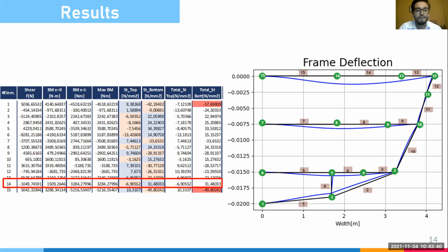There is a positive bending moment, and the fibers at the top are in contraction, so it makes sense; according to the graph they are consistent. And another thing, in that part of the beam we have to take care because it's absorbing a lot of energy, so it's a large deformation, and it could fail because of ductile modes of failure as well.